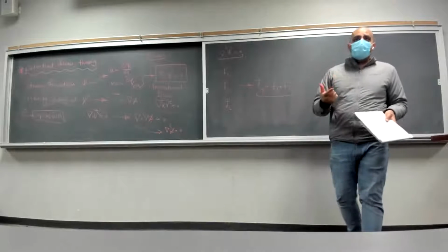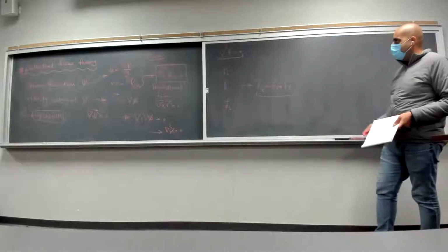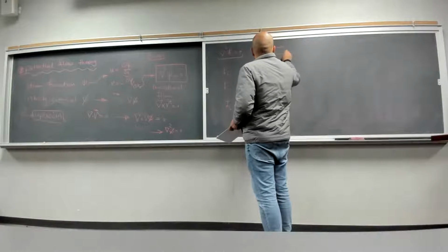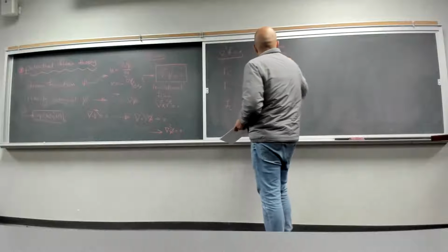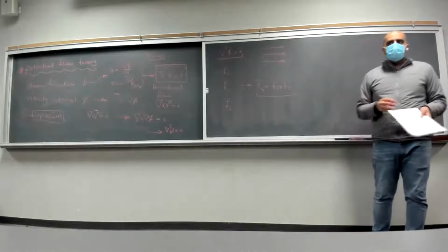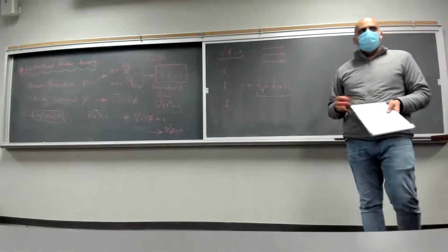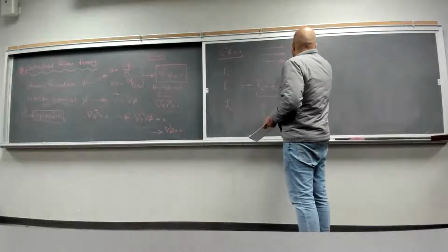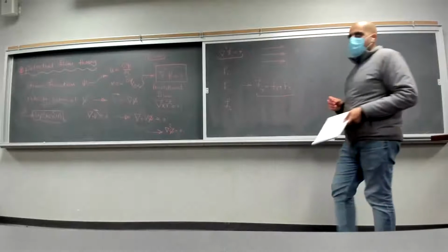To give an example so you can understand better, we're going to introduce the elementary flows we're going to use, like this flow, uniform flow. Velocity doesn't change. There is no change in direction. There is nothing, right? What is the velocity distribution for this? U equals V infinity, right?